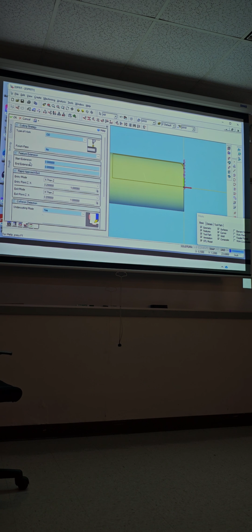See that? I used that for the engraving. So it's telling me 0.200 and 1.8, so then you just copy that to the other one. X then C, so 0.200. And actually you can do the math too, right? 1.8. To blend, yes. All right, so those are my numbers. Just revise them. Start extension, remember, 0. Only on facing do you have to do the crazy math. For the rest, everything is gonna stay, leave it alone just like Corey said.